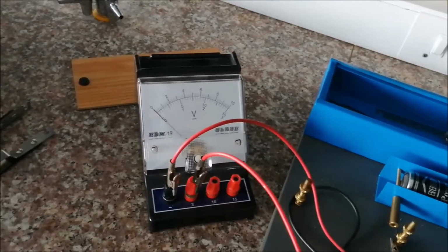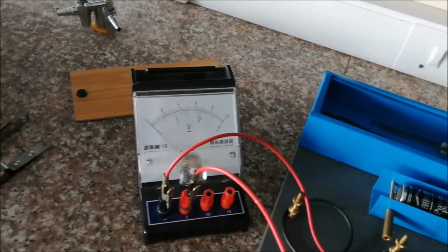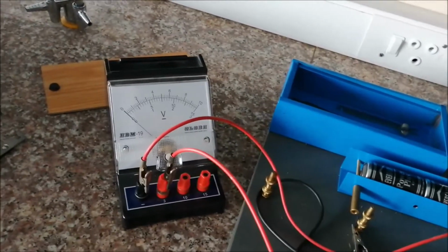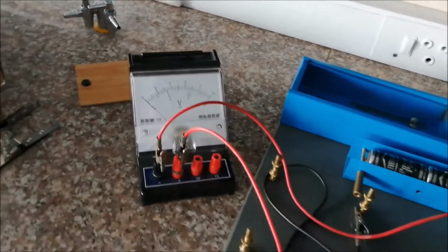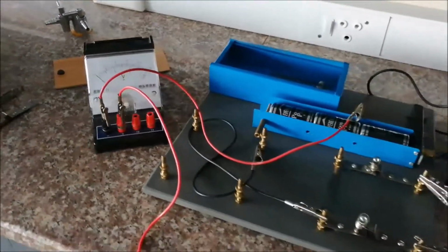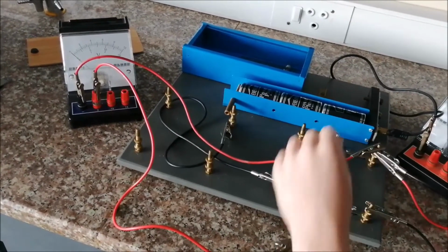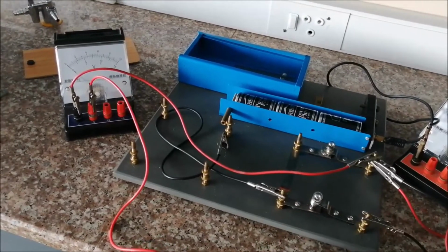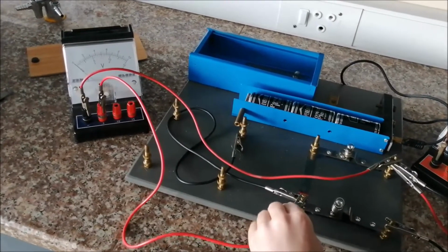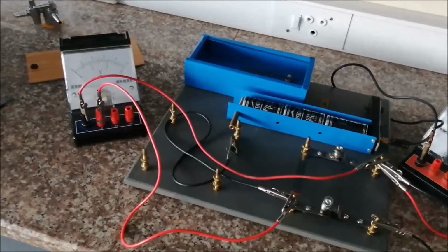Here we are getting an indication of how much electrical potential energy we have as a result of the difference between 2 points. You can see we've got two leads. Unfortunately I've run out of black and red leads, but they have to be connected in parallel, so let's go ahead and do that now. We still have our parallel circuit, so we'll connect to the first terminal that forms part of the parallel circuit, and then to the last terminal. Now we will connect the circuit up completely to the battery.